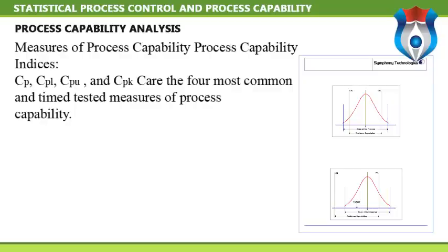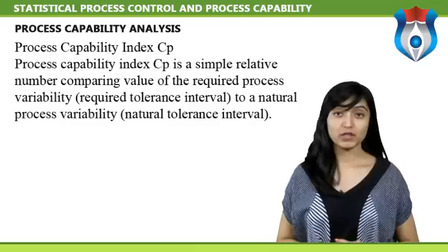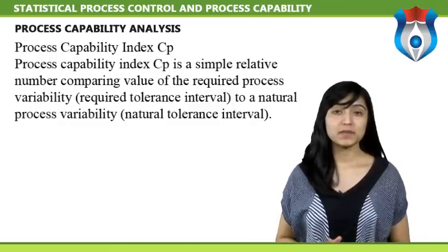Process capability indices can be used effectively to summarize process capability information in a convenient unitless system. CP and CPK are quantitative expressions that personify the variability of a process, its natural limits relative to its specification limits, customer requirements.